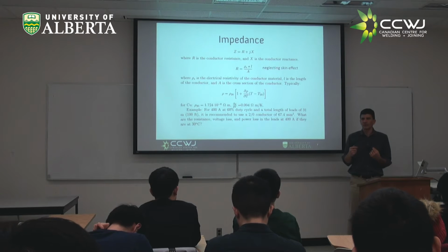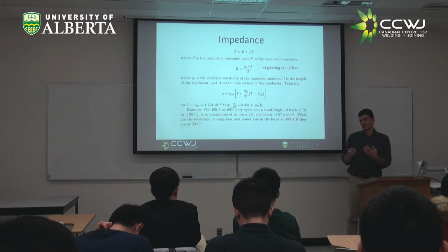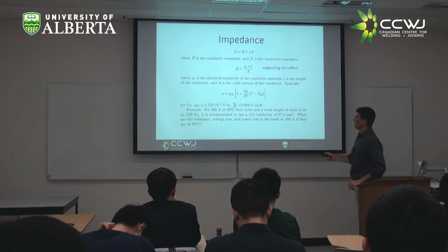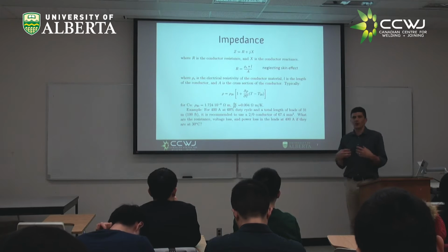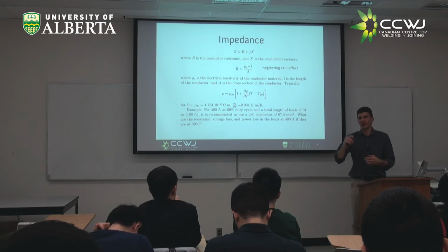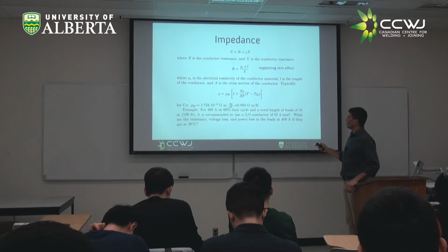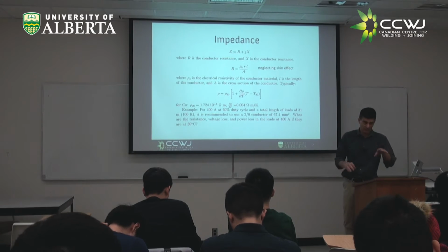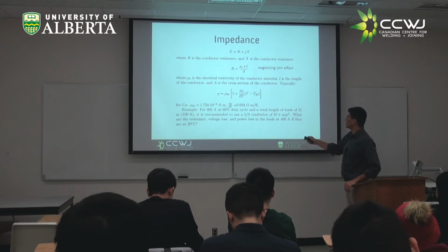But it's good that you know, because if you go to work at Supreme Steel, and all of a sudden somebody tries to sell you a super sophisticated waveform machine, maybe it's good, but you better know that you're carrying the machine floor by floor, right? Those types of things. Okay, and so I uploaded for you a lot of material that is super cool about how to select the leads for welding. You have everything, like the American gauge, all kinds of things there. If you look at that material I uploaded, it says in this case, you should use this 2/0 conductor. It's all explained in there, that has this cross-sectional area.